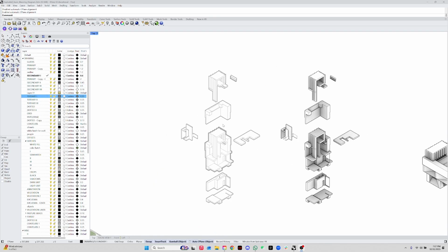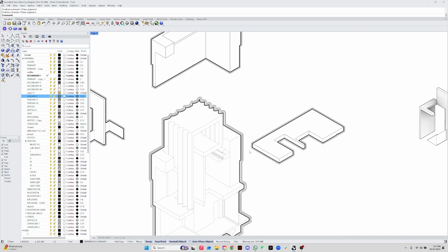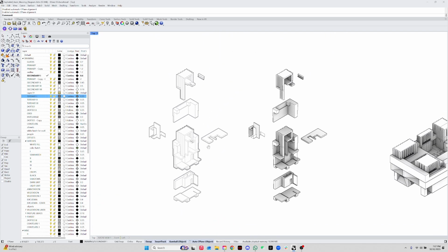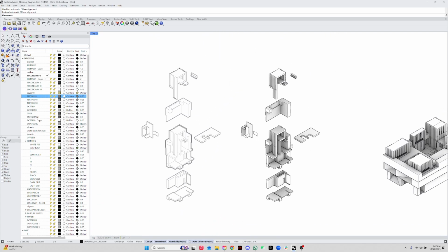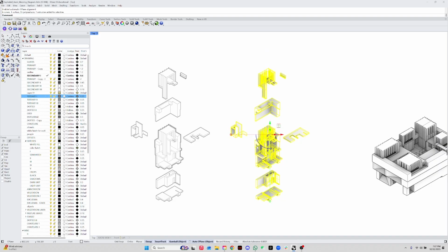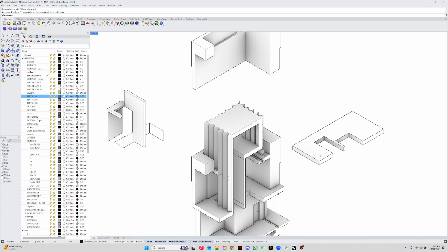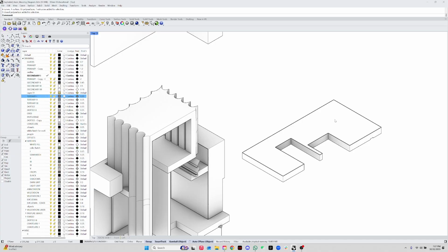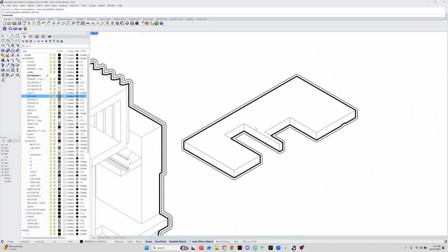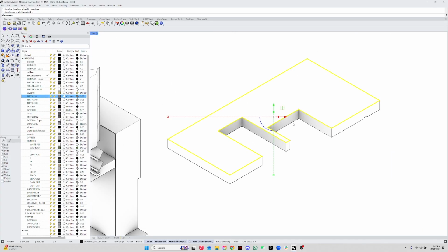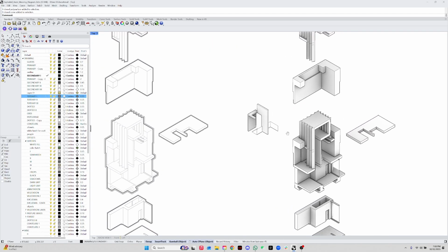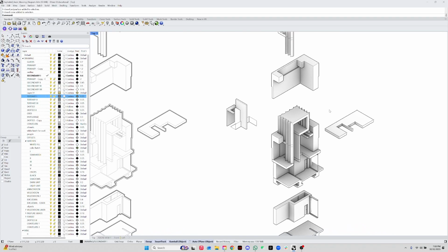Okay, now that we have our line work and outlines, and everything picked and resolved and clean, we're going to move into hatches. Now on hatches, the reason why we're turning the model, using the script that I gave you guys, on this angle is so we can directly map the hatch on the surface itself, and basically the hatch is going into the actual surface instead of just being a flat surface. So it's actually going to get the angle of the model itself. That's why we're turning the model.